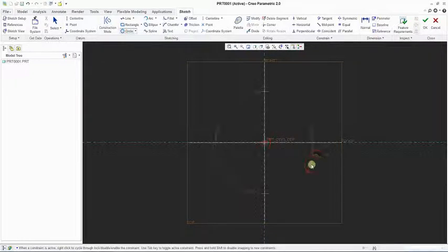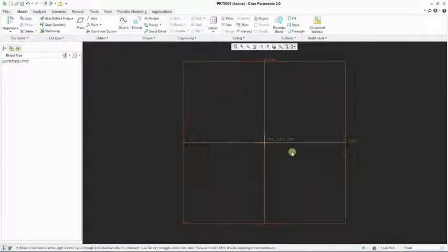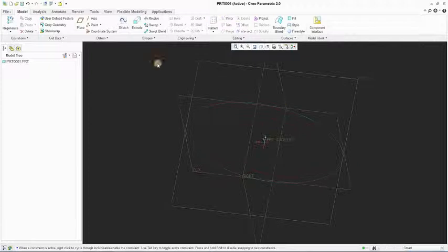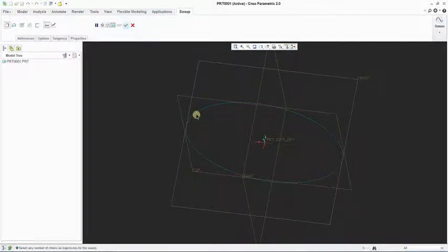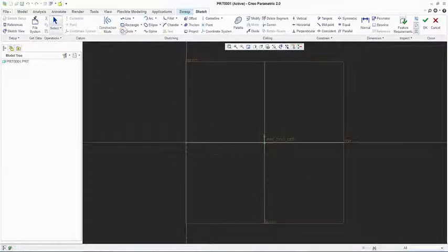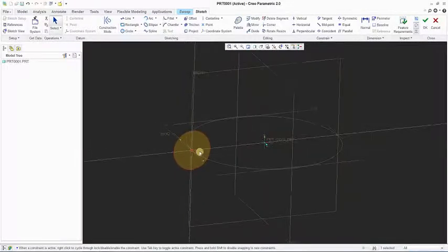Here what I'm going to do is I'm going to say okay, I have a circle. Now again I'm going to go for sweep. I'm going to select the profile. I'm going to say let's say sketch and I'm gonna go with the circle, right? So what we can do is in this place, let's say somewhere around 20.